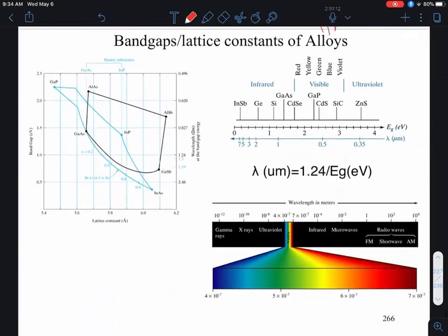All right. Pretty early on, people were able to get red LEDs, and then with a little bit of tweaking, they were able to get yellow and green. But try as they might, there was nothing available in the blue part of the spectrum, okay? Because for blue, you need much larger band gaps, as I pointed out, right? You need something of the order of 3 electron volts or so. And the gallium arsenide phosphide system, gallium arsenide is over here, phosphide, it simply couldn't get up there. So the whole field of LEDs hit a kind of dead end.